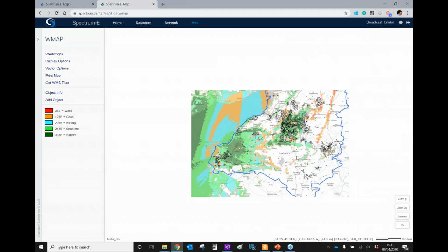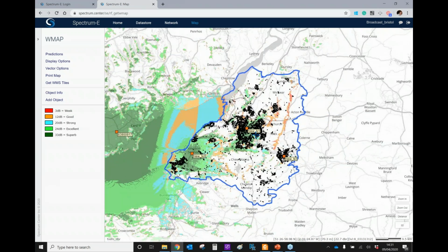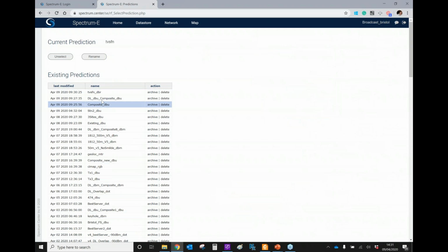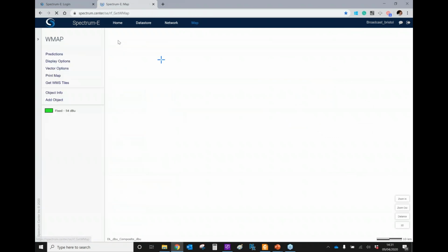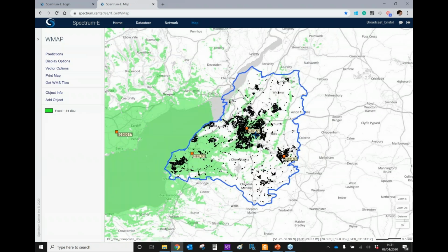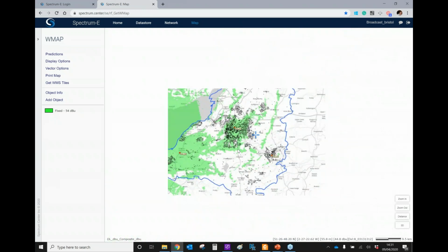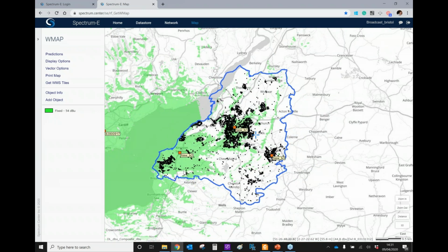So once we're happy with this, what I'll show you now is have a look at some of the population covered functions. So the population covered will be based on our predictions. So we've got our prediction of the full number of sites, including the one across the water here. So we can see that the green area identified covers partially some of these sites. And what we want to do is really quantify that for use in reporting the number of population points, and also we're able to identify and quantify the percentage of the polygon or a number of polygons within our shapefile.